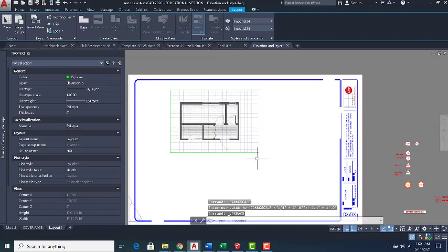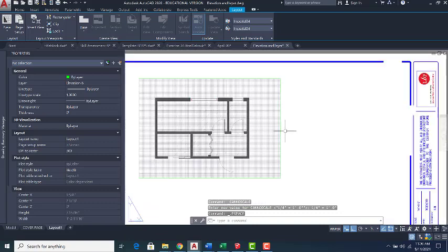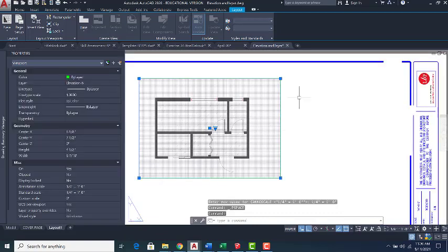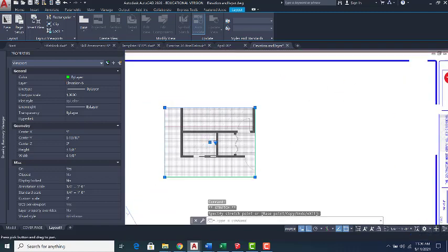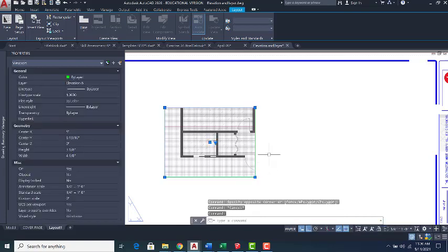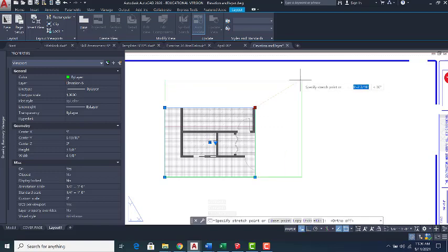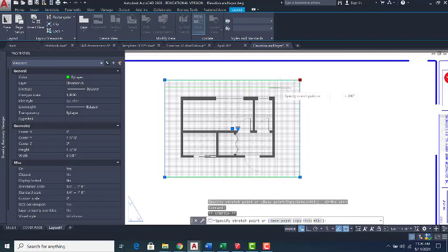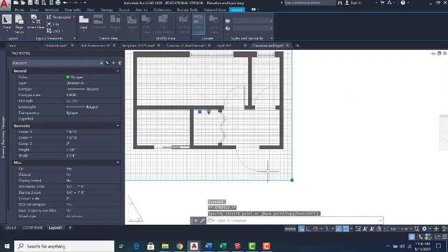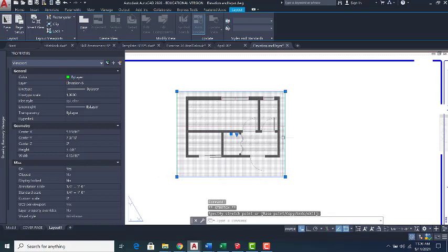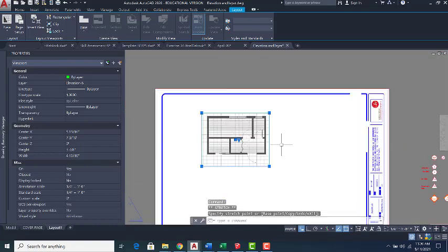And remember, if the window is too big or too small, you can always click on the line and manage it with this handle. You know, it might be, oh, it's not what I wanted. It set the scale, but you cannot see your plan. It's not a big deal. Just click on one line of your viewport, click on this handle, and then you can turn off your ortho, and you just make it the right size that you want. So that's good. I think it's nice.